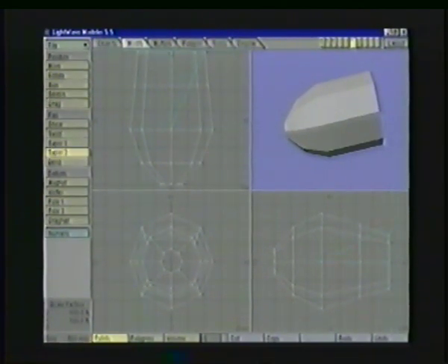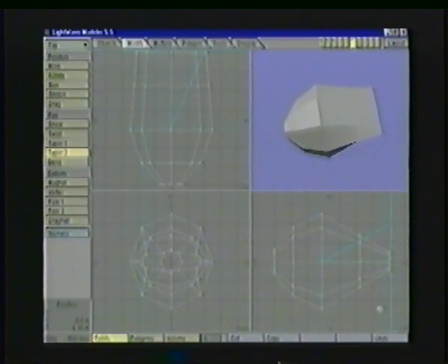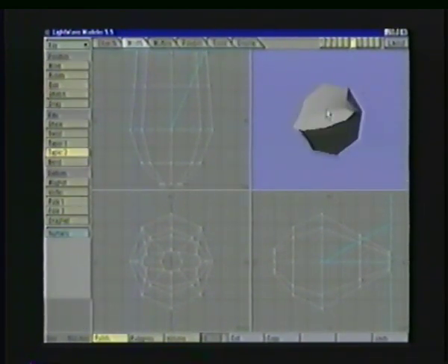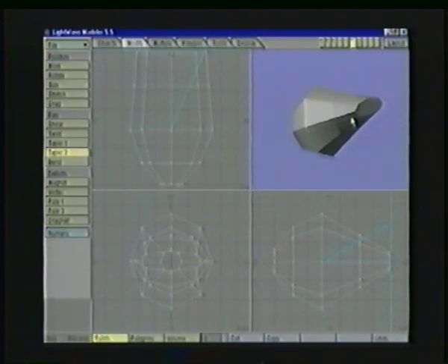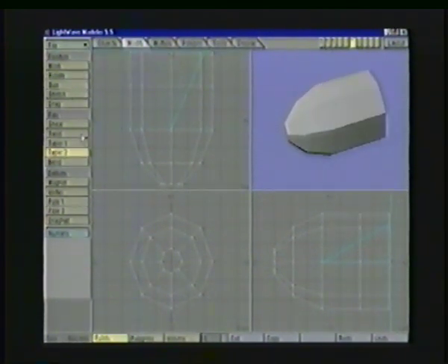And here goes the taper, but you can see if I pull straight down with my mouse, I can taper it in the y-axis, but I haven't really tapered it much in the x-axis. This is where the Taper Evenly tool comes in, Taper 1, and that's the one we want to use. So I'm going to undo this and go back to Taper 1 and repeat the taper.